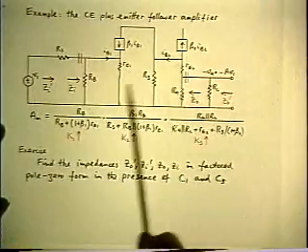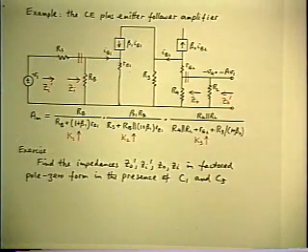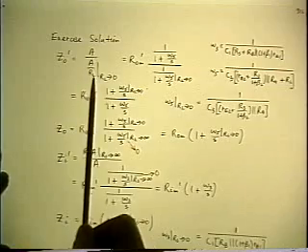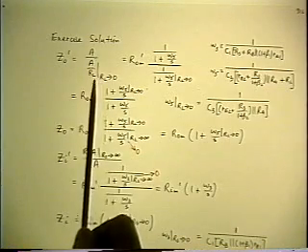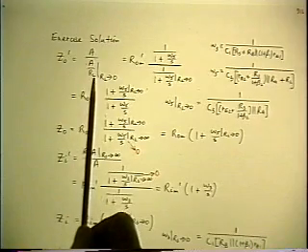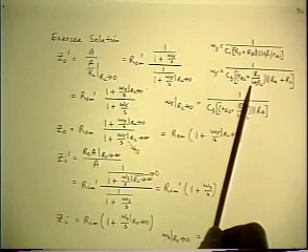So here we have the capacitors in place now, and we want to apply the impedance formulas. So here's the solution. The outside output impedance is found by applying the output impedance theorem to the modified gain function in the presence of the two inverted poles, omega 3 and omega 5.